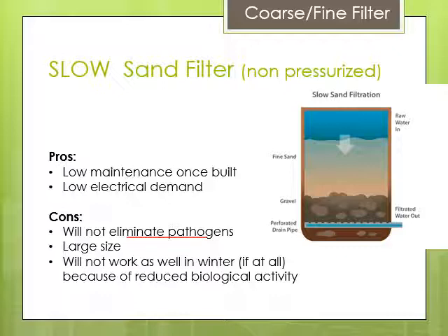Cons: they can be very big, large tanks, large surface area. And a big con in Canada is that they don't necessarily work well in the winter because they freeze, right? That other one was below the ground, so there's some ground temperature. So maybe in Niagara, there are times when it might actually work. But you definitely have reduced biological activity in the winter. So something to be mindful of.